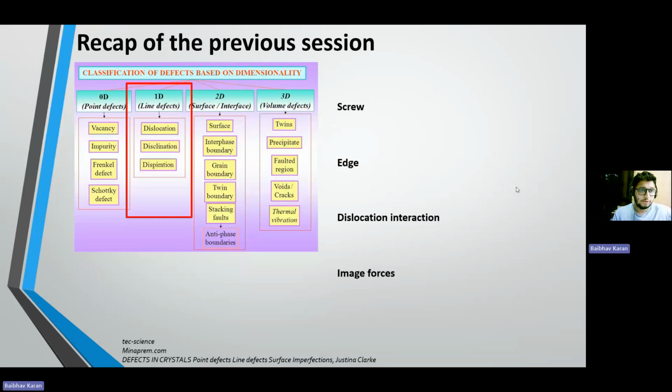And coming to the theoretical strength, remember where we began the definition of defects. Remember about theoretical strength, right? What is the theoretical strength of steel? It's around 8 GPa, right? That means if we do not consider dislocations or any defects in the material, the strength of the material can be in terms of gigapascal.